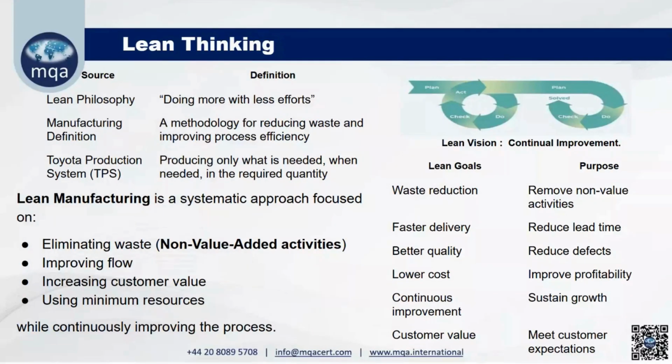I get it now. Thank you. Two ways are there. One is to increase the capacity of the blending machine, or the buffer tank, right? If you increase the capacity of the buffer tank, then you can fill it for 30 minutes. First time will be wasted, but continuously you can feed it, right? Yes. Okay, thank you, sir. See, line balancing is time balancing or capacity balancing. If you're filling in 15 minutes, then you have to produce in the buffer tank in 15 minutes. That is the only thing.